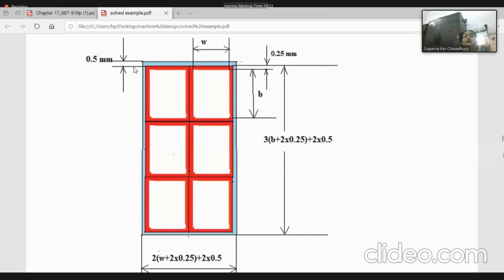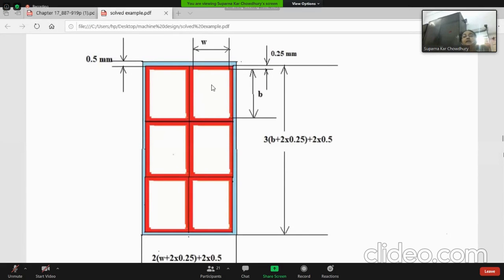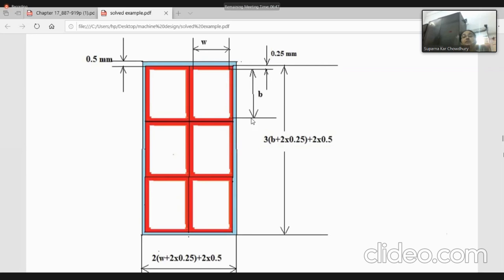It also acts to arrange the conductor and bind the conductor in space, and also provide the insulation. This is the common insulation. So this individual paper insulation is 0.25, and this outer insulation is 0.5. So if it is a six conductor, then we arrange it in this way. This is height wise 3 and width wise 2.